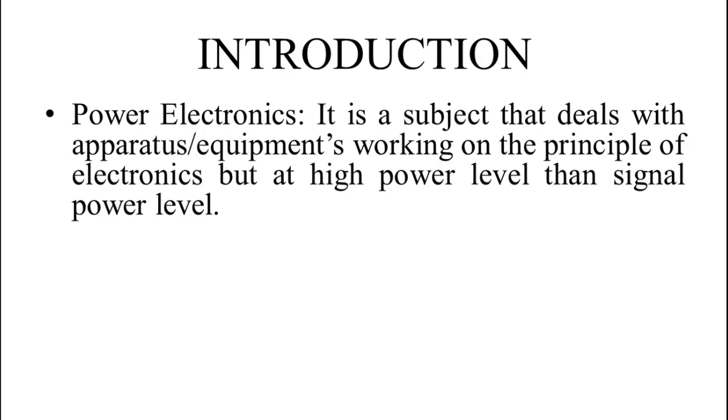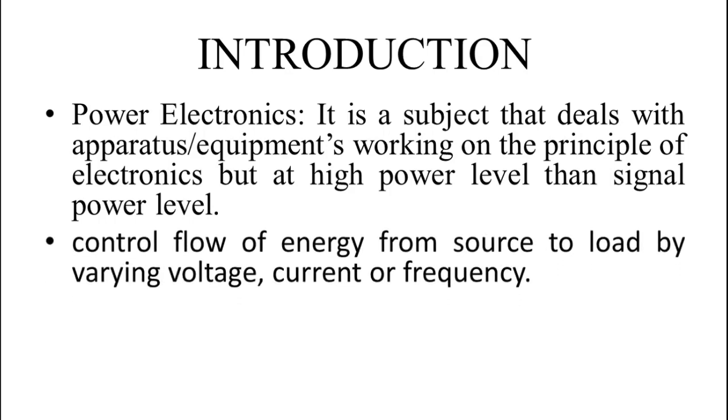Power electronics in the electrical world has the main role to control the flow of energy from source to load. How do these power electronic devices control the flow of energy? They control the flow of energy by controlling voltage, current and frequency. So, it is appropriate to state that power electronics is the application of solid state electronics to control and convert electric power. The power electronics era started with the invention of the SCR in 1956.